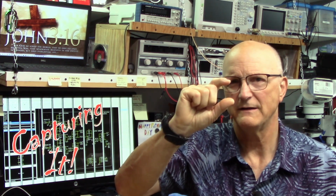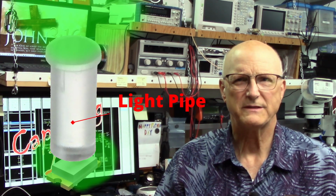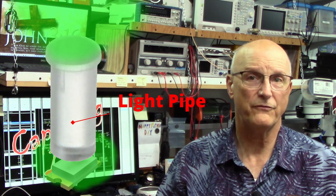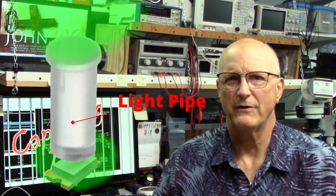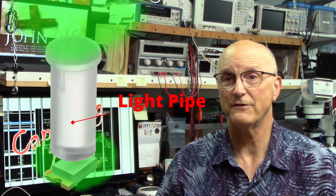With leaded devices, we can mount them at any height we want in order to have them extend through the holes in the front panel. Furthermore, machining the front panel isn't too critical because the leads are relatively flexible. Now, we could also use surface mount LEDs. The problem is the distance between the PCB and the front panel and having their light be seen through the front panel. Now, we deal with this with what are called light pipes. Light pipes are mounted to the front panel and extend through the front panel to a short distance away from the LED. These are like large-scale fiber optics, which transport the light of the LED to the front panel.